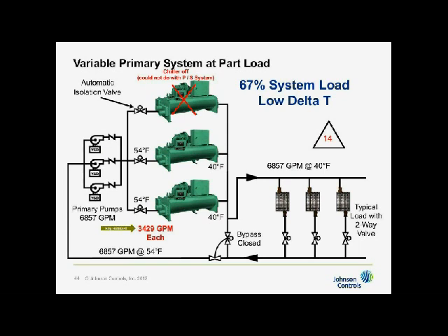Just overpump these. And can I overpump them? Of course I can. Chillers can handle up to 11 or 12 feet per second. Typically designs are around 5 or 6 feet per second. The design for the chillers that we picked for this example that we run calculations on later is 5.8 feet per second, and you can turn it down to 1.5. Okay, and you can go up to 12.